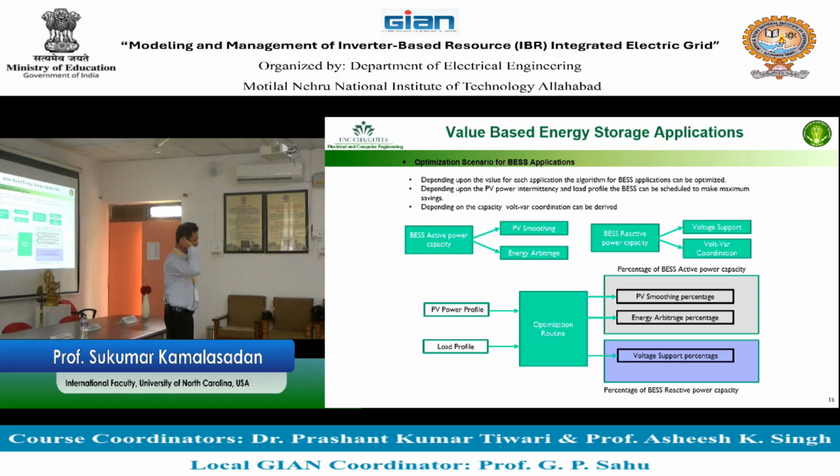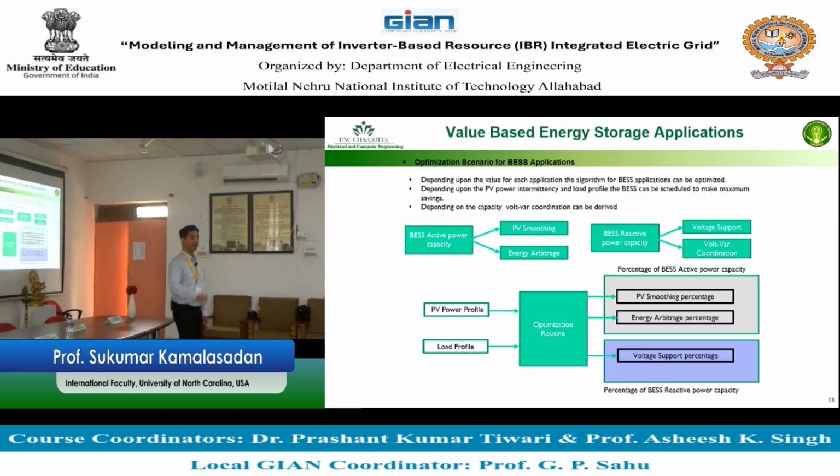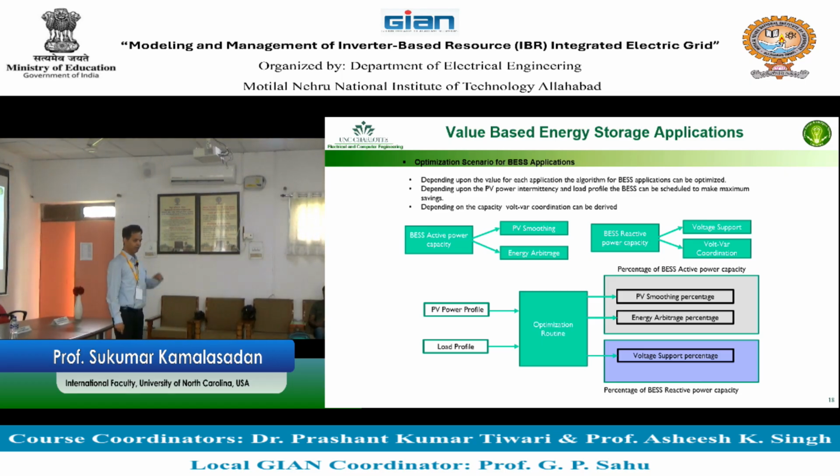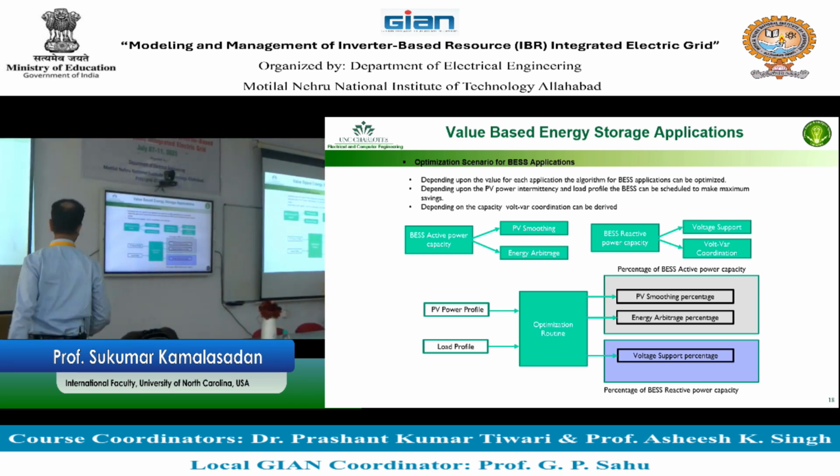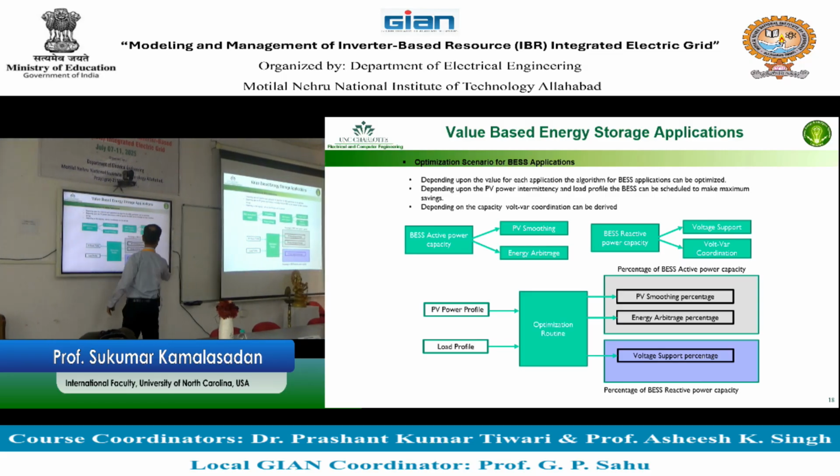Reactive power support, as opposed to voltage support, is based on pushing a set reactive power from the inverter. So I will say that I need 50 kVAR. I will have to put in 50. So my controller signal is reactive power, controlling reactive power, not voltage. So I'll be getting 50. Now let's assume that I want reactive power and voltage control. I'll be doing 50 plus that waveform. So the waveform for the voltage, let's assume that it is something changing. You will be seeing the reactive power also.